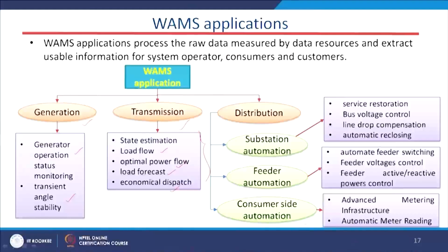Load forecast is also very important. If we can forecast the load beforehand, knowing how much power we have in hand one week, two days or one day ahead, then we can go for power dispatch. We can easily decide how much power we can supply to a particular customer or a particular area. And we can also do the economic dispatch part.